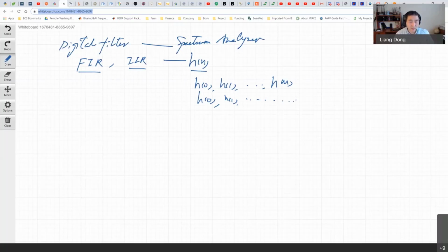Remember that we're not just writing y[n] equals h[n] convolved with x[n], but in implementation, y[n] has a part where x[n] is convolved with h, meaning I'm taking the previous x[n-1], x[n-2] as well. It should not be h[n], meaning the entire system, but just bear with me here, let's say h prime. But you still have this part, you still have some feedback.